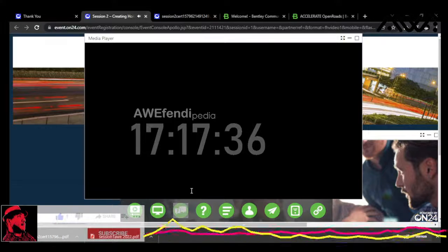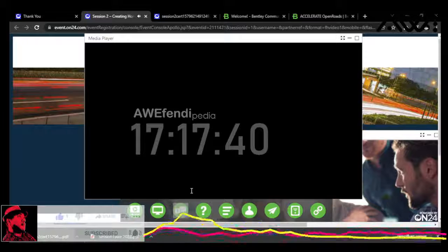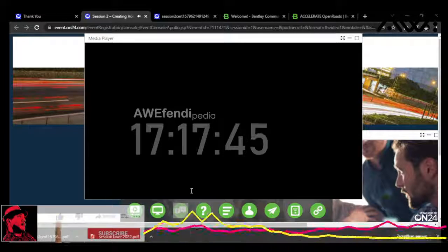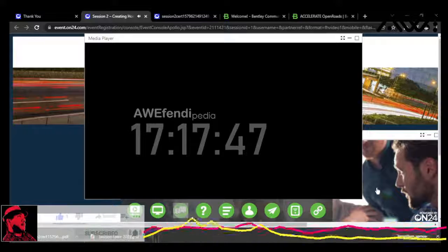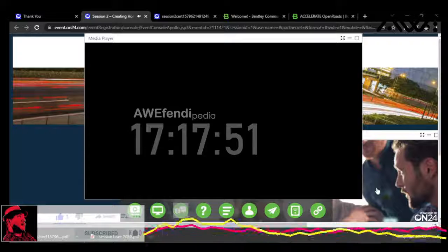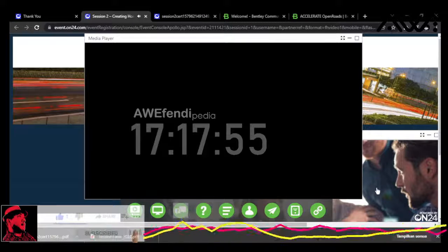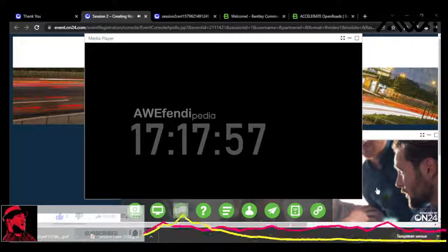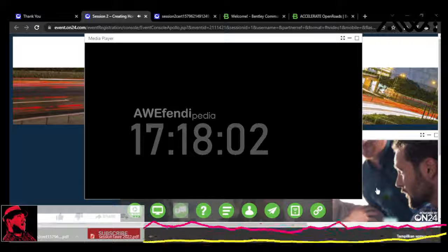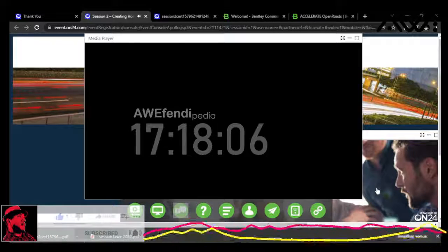Now, in this instance, we are more or less going to hold the horizontal location of the existing centerline. That's our objective. So, a couple of things to point out. There's an existing centerline monument located off the topo. This was picked up in the survey. So we have an existing monument on the western end, and there's an existing monument on the eastern end as well. Okay, so we have some known monumentation to begin from, to hold to.